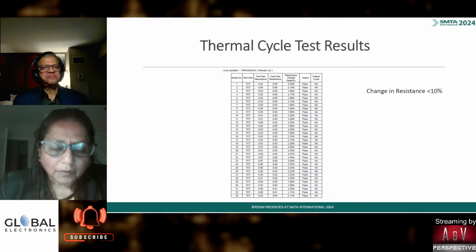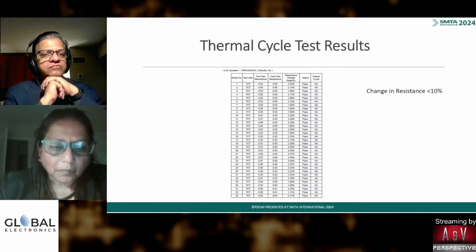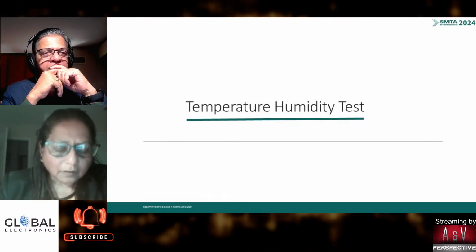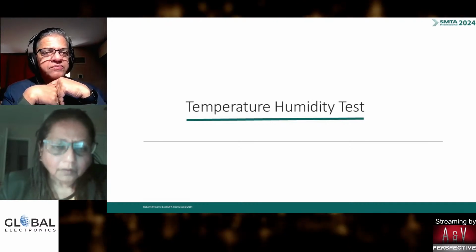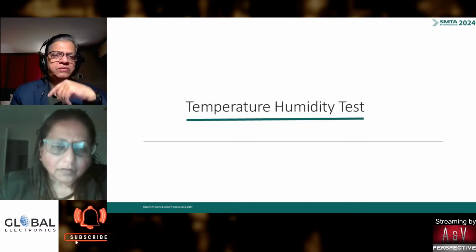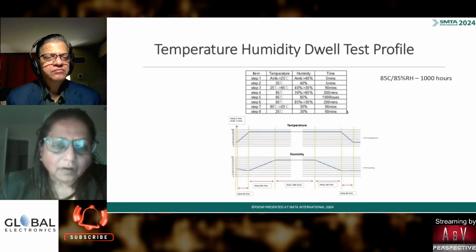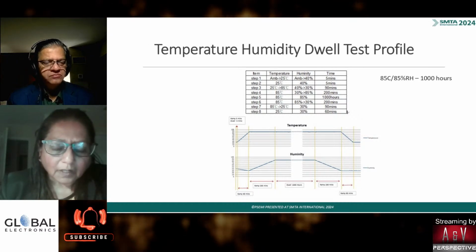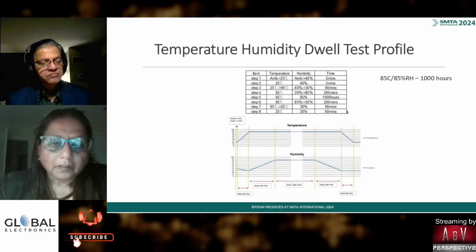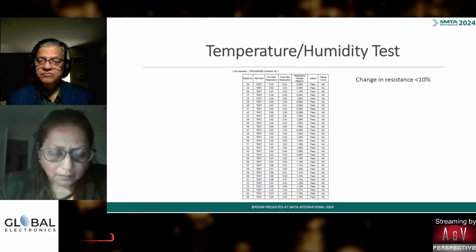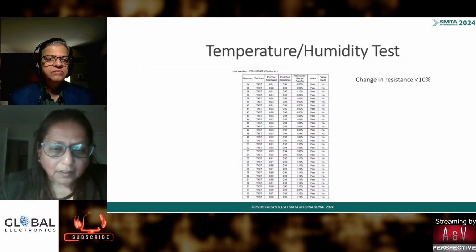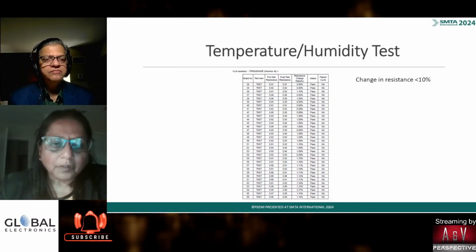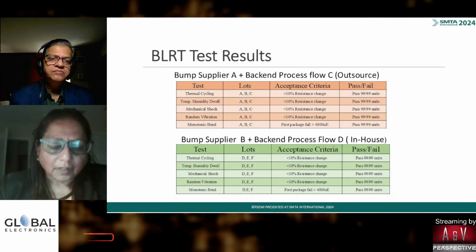In the packaging substrates, we have already gone to ultra HDI, 2 mil lines, 2 mil spaces, going into 1 mil line and 1 mil space. Finer and finer vias, 30 micron, 40 micron. So yes, the designers have to learn to align to what the needs of the industry are, and prepare to design in that form, and also to keep in perspective design for manufacturability, design for reliability, design for environment. All these things are becoming more and more critical as we approach future designs.